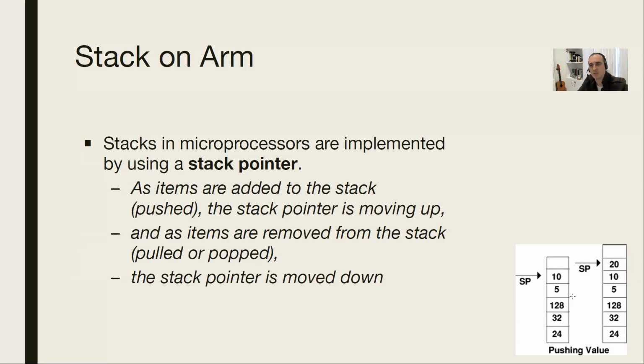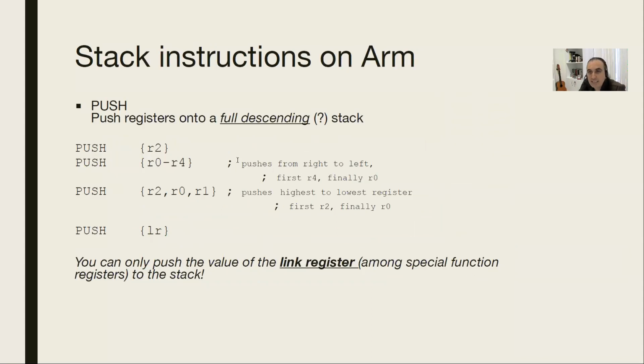So if I say stack memory, please get that I'm talking about that dedicated part of the memory, which is only used for stack. Okay, so let me get to my slide. So guys, if you want to put a value to the stack memory, if you want to push something to the stack, you can only get it from the registers. So you need to have it in the registers beforehand. And you will use this notation.